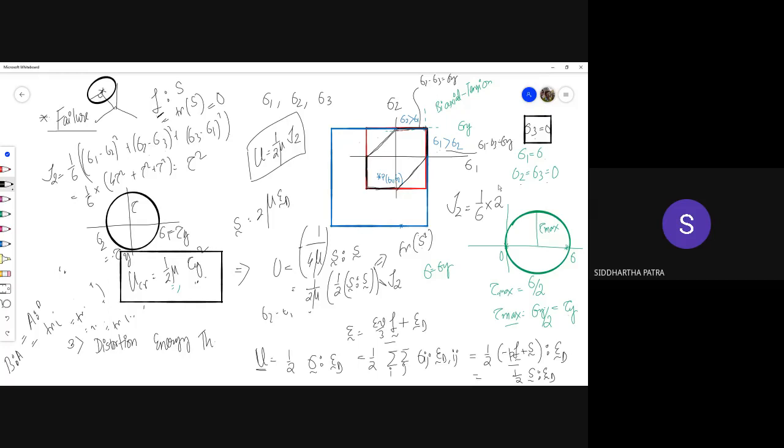Yeah, twice sigma y squared. Okay, or 1/3 sigma y squared. Therefore the value of U critical for failure is 1/3 sigma y squared. So we would compare these two values of the critical distortion energy, because the distortion energy theory predicts that in each case the failure occurs because the distortion energy reached the critical value.